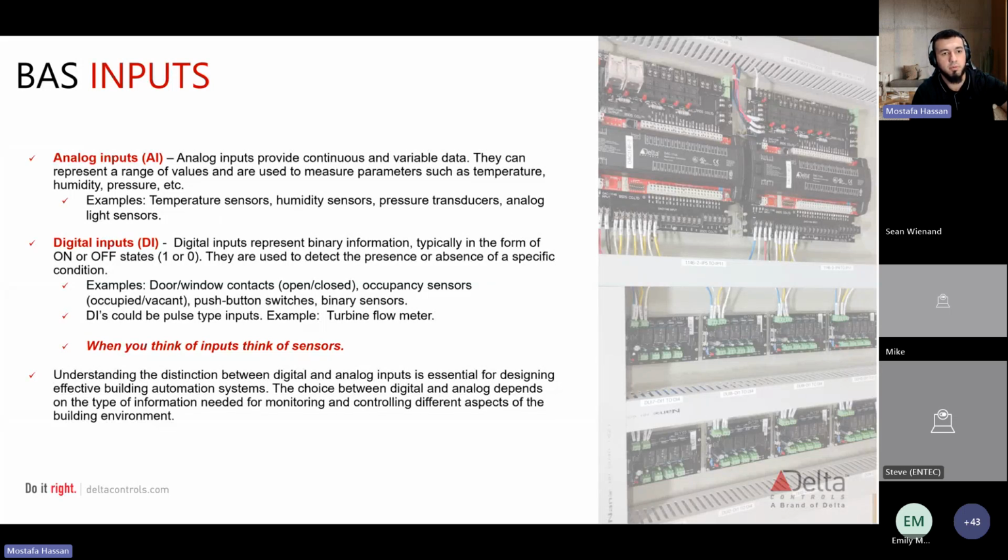The analog side provides continuous but proportional data, right? Temperature is proportional. That's why it's analog, right? So it's calibrated via voltage. It could be calibrated to a specific electric signal, and depending on the range of temperature that you expect your system to experience, you're going to calibrate that voltage to that range, right? So that's why that would be analog with temperature.